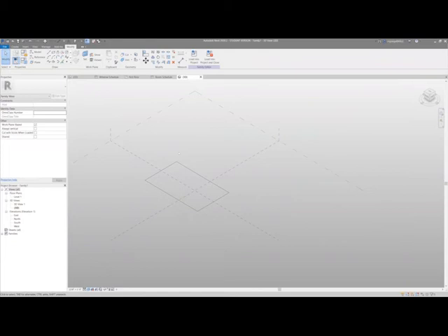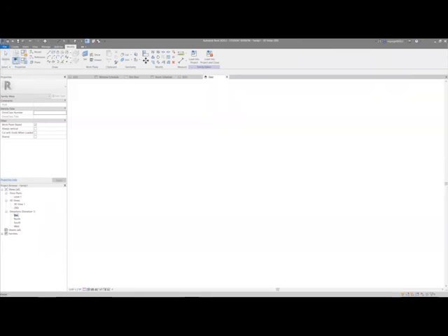What I said beforehand about Revit being all about setup is true in everything. So if we want to associate these planes on separate levels, we'll go to this elevation right here, take elevation 1 and just make more levels.